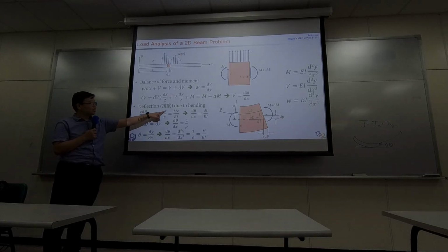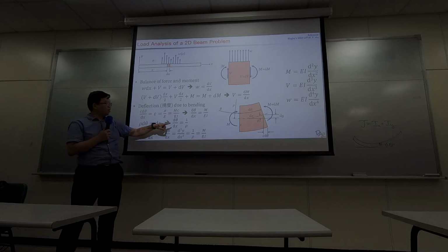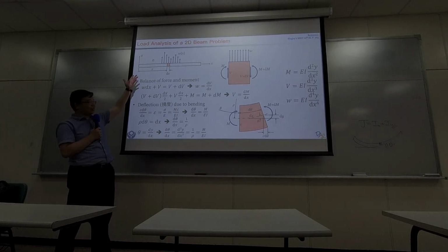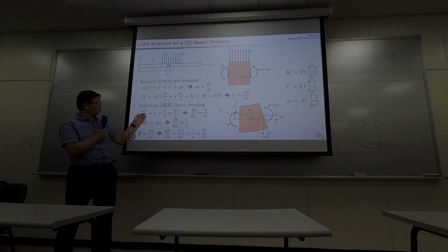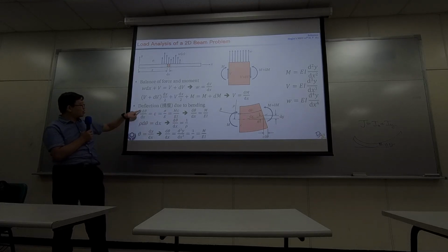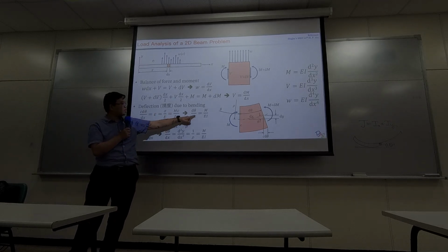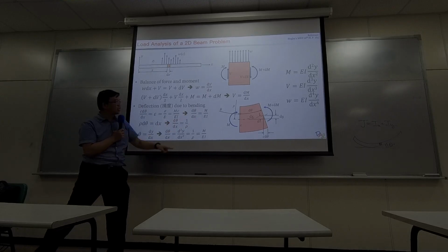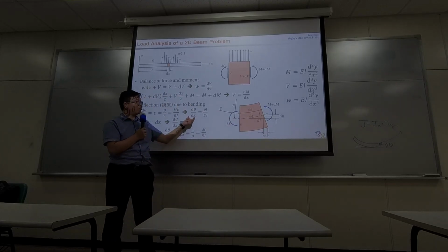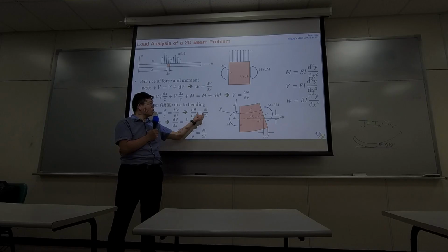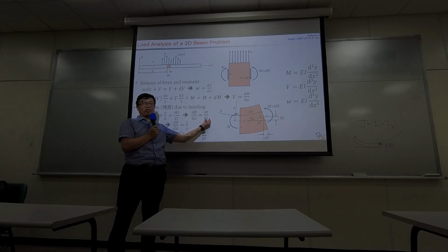And strain equals what? Stress over Young's modulus. And stress equals what? Mc over I, from what we have learned earlier for the beam. So from here, at the very left and the very right of this whole equation, we end up crossing out c from both sides. So d theta over dx equals M over EI. That's why we have this. If you want to study the increment of this d theta, it's related to how much moment is being applied, the material property E, and the cross-section geometry, I.